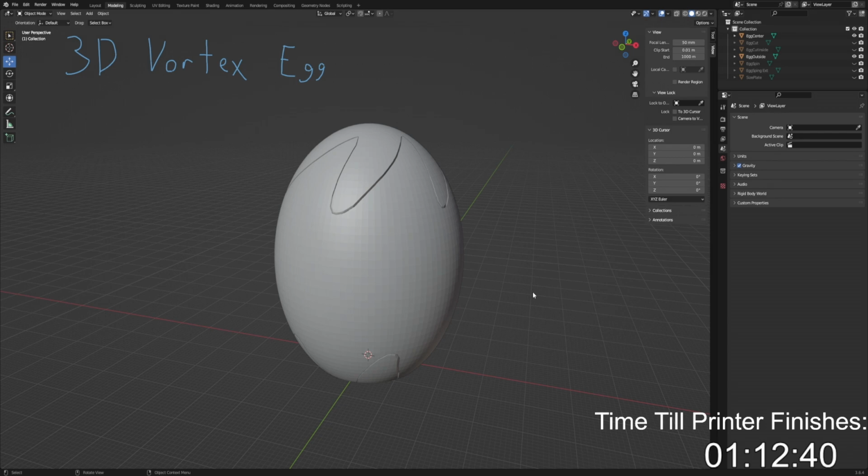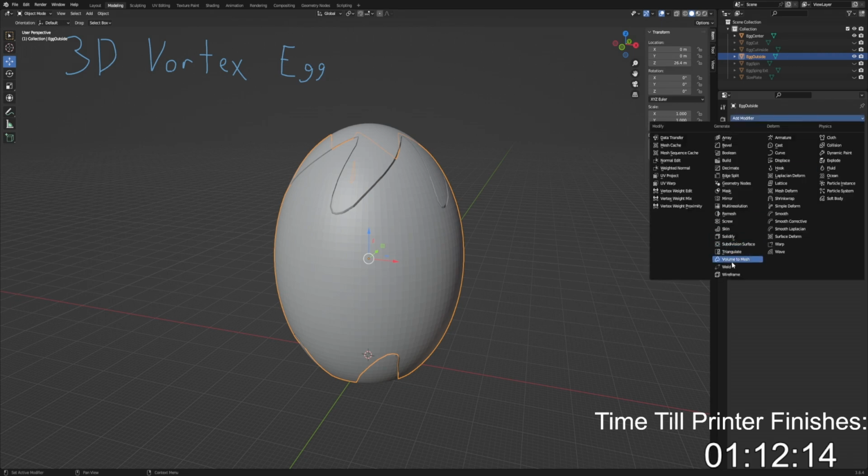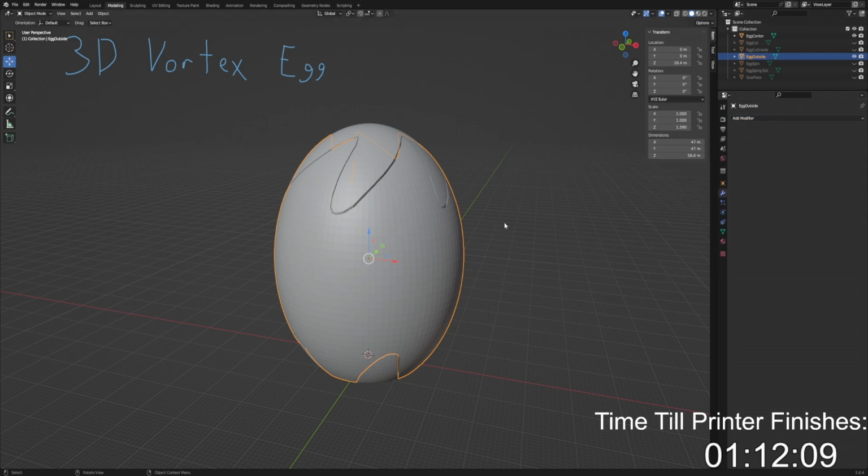So that was fun to learn. Honestly, there's definitely a lot of tricks that I need to learn. Like when changing things, be careful, because if I click on an object here, scaling affects a lot on certain things. Like if you bevel it or do modifiers on it, like, what was I trying to do? The screw modifier. It takes into effect that scaling thing and it really messes it up. So try to keep your objects the same.